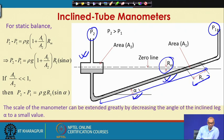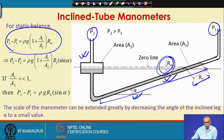So, now again I can write the balance equation for static balance. P 2 minus P 1 equal to rho g into 1 plus A 1 by A 2 into R m. This follows straight from the discussions on well type manometer.